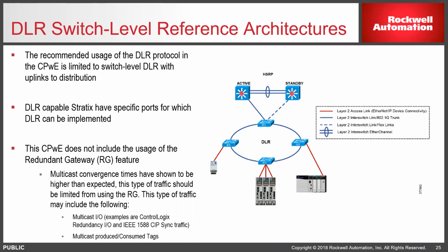So one of the main things when we're looking at the uplinks is what technology we want to use going out of the device level rings when we're talking from switches to that next level of stacked switches. How do we want to talk there? And one of the main ways that we typically do that is going to be through FlexLinks. And so later on, you'll see the different testing that was done, and the preferred method is FlexLinks there typically.